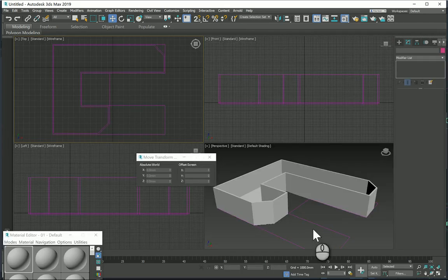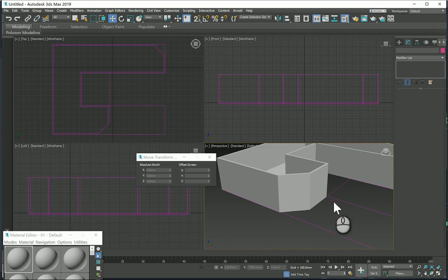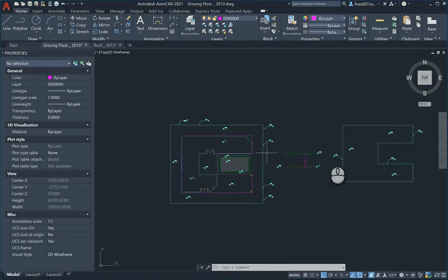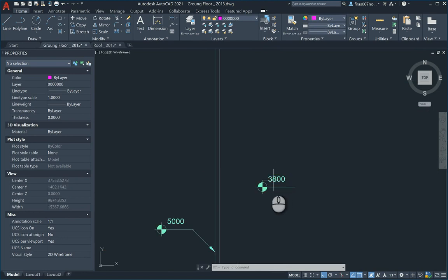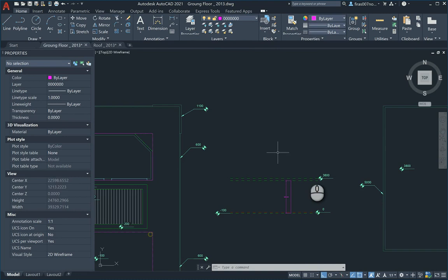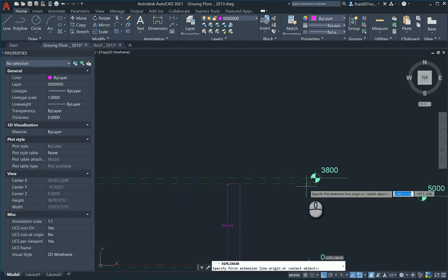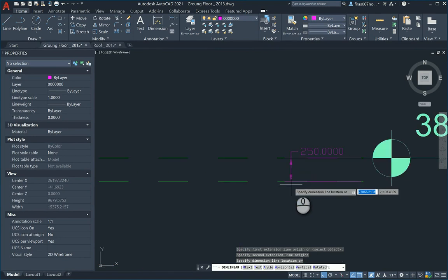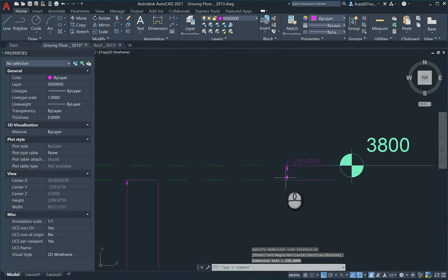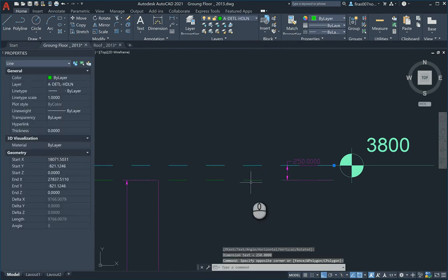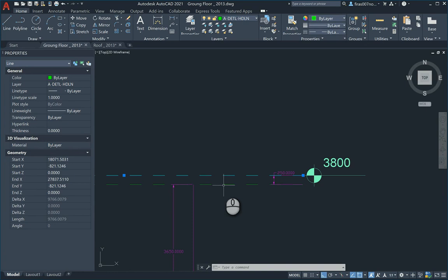Okay, now second magenta line. Now second rule applies. It's a horizontal surface, so the Z or the level will be 3,800, whatever is written in AutoCAD, and the extrude, we said it should be minus 200 or 250 or minus 300 even, depending on the situation. So you remember that we got this from the section, and it's in here minus 200. So I'm gonna put it here, and the extrude will be downward that way. That's why it's minus 250. Some people want to put it in 3,650 with a positive 250.